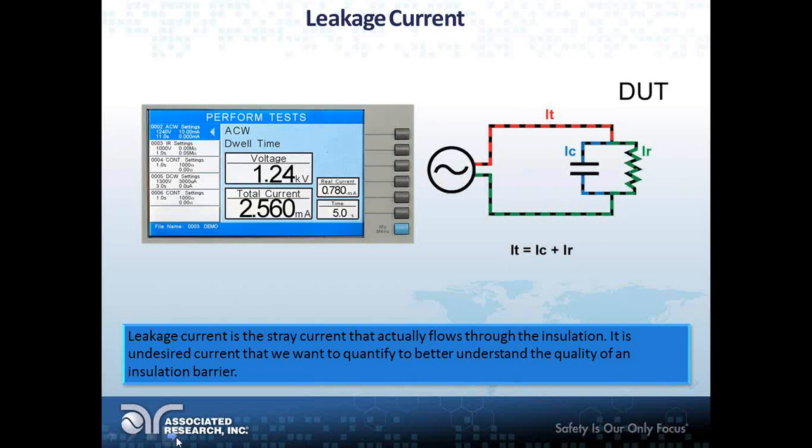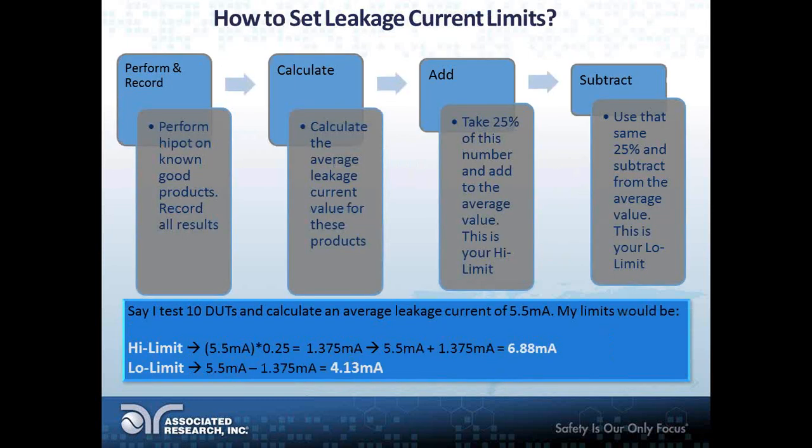That is very common to see with a Hipot test. So that's important to remember moving forward. So really, how do we set leakage current limits? It's tricky because most standards don't actually give you limits for leakage current values. There's a couple of exceptions. There's some standards out there that do give you some leakage current limits.